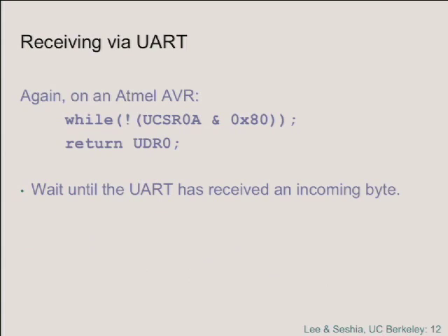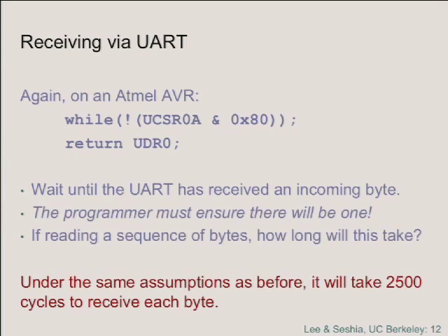Okay. So we will... wait, I have 1 more minute, so let's not stop yet. So this could take up to 2,500 cycles to receive each byte. So that's a polling mechanism. Interrupts are quite a bit more complicated and a lot more powerful and a lot more interesting. Okay, you can use the hardware a lot more efficiently, but they're much more dangerous.